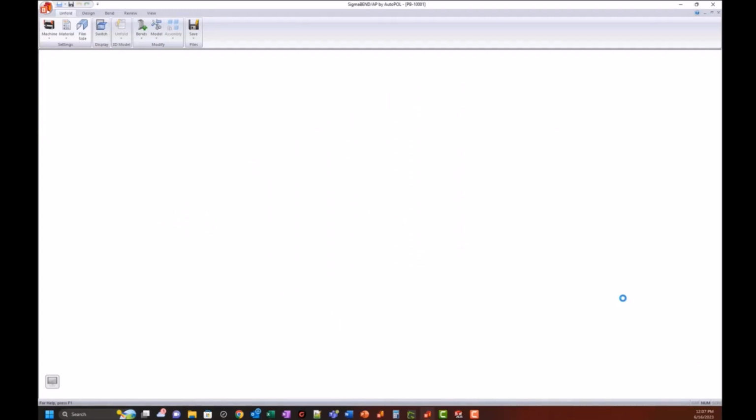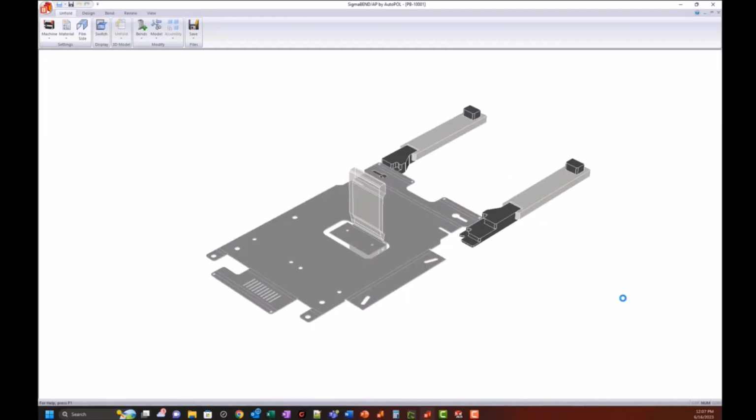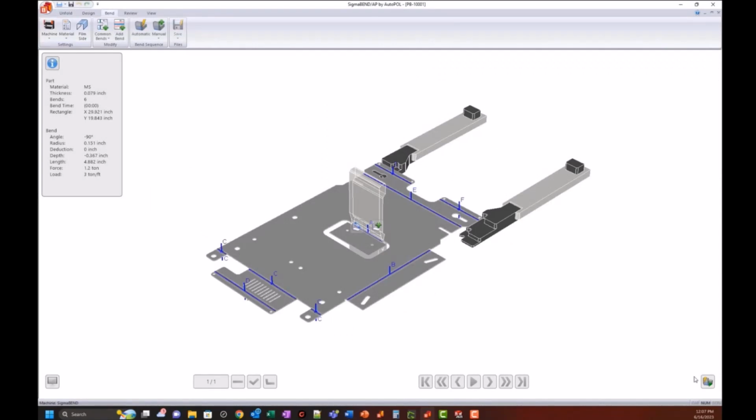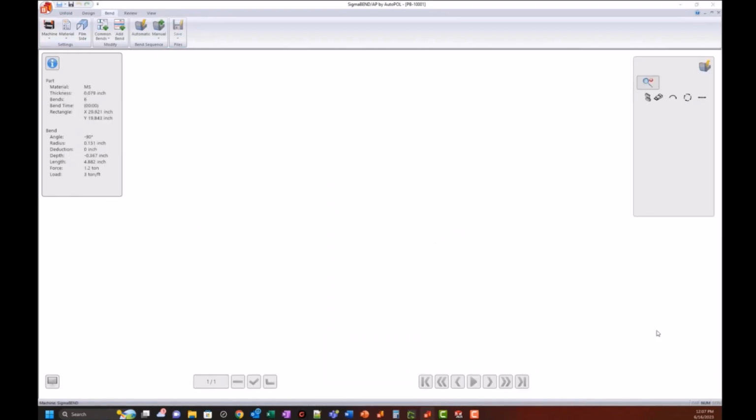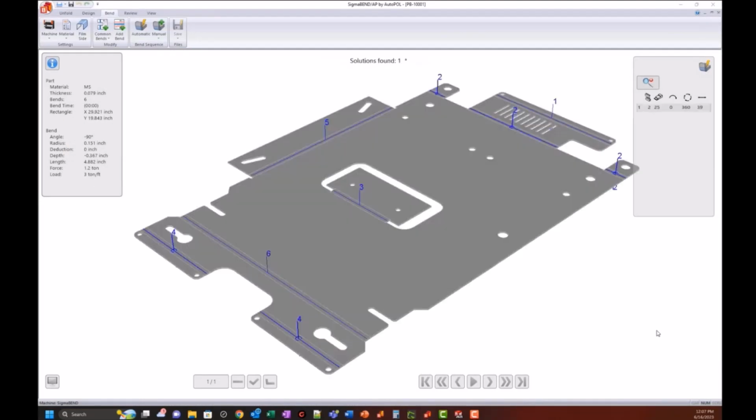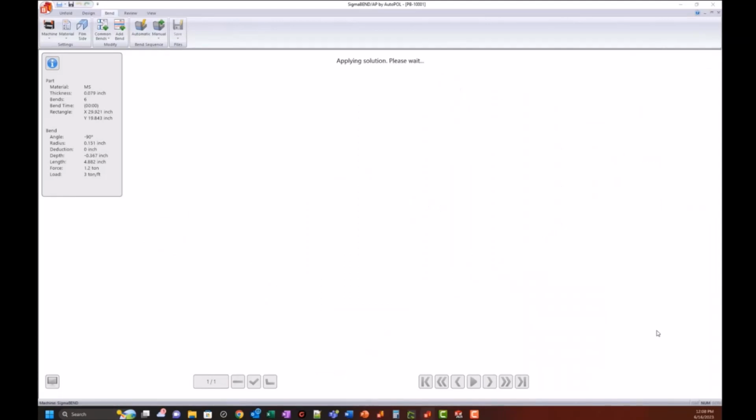So we've got a pretty complex part in here first. Some common line bending, some internal bends there that are going to require a smaller station. I'm just allowing the software to program like normal, generating our flat pattern, allowing it to solve for the best sequence, the things that are going to minimize within the program itself: station changing, back gauge movements, flips and turns, all of that.